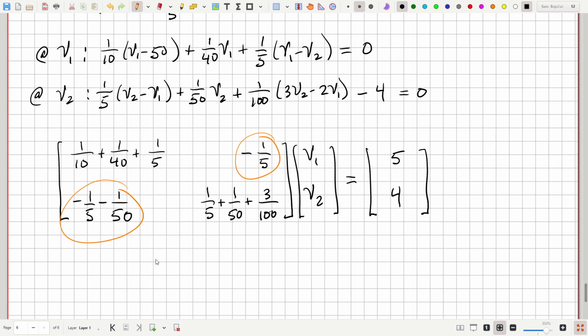And so if we solve those, we find that V1 is 55.0 volts, and V2 is 64.4 volts. I'm sorry, I got that backwards at first. Okay, so the key takeaway is when you have dependent sources, you cannot assume that your conductance matrix, the G matrix, is symmetric.